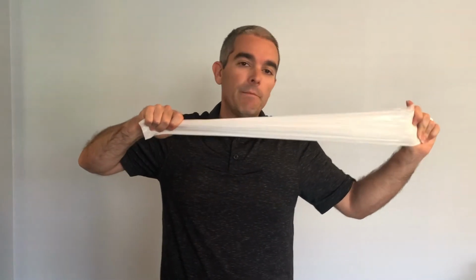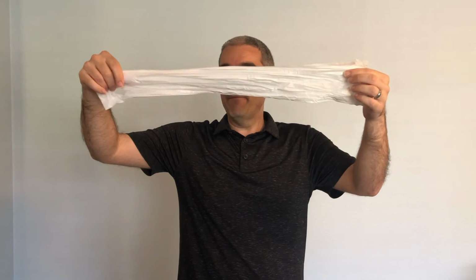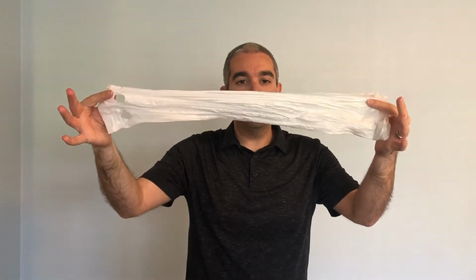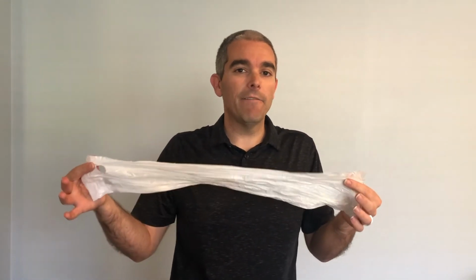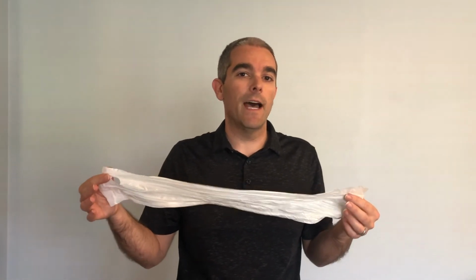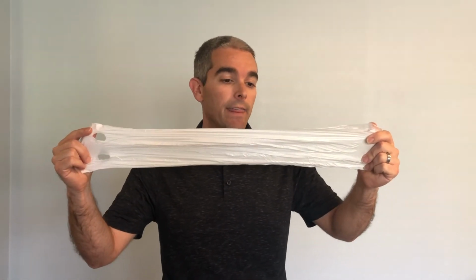Basically, we pull on it and pull on it, and now it's stretched, right? So this member is now permanently deformed and is longer than it originally was. Yielding is a problem because it leads to what we call excessive deformations, and excessive deformations in steel members is not good. If this was supposed to be a certain length, now it's a couple inches longer than the original length.